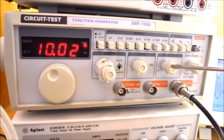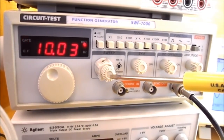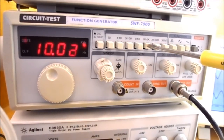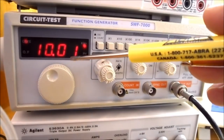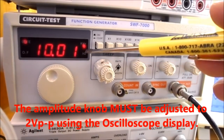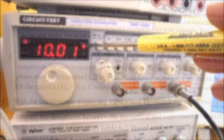All the knobs should be pressed in. This one should be fully counterclockwise till it goes click. You want the power button on. You want to select sine wave. You want the range to be times 10K. You want the OSC button in the out position. So we're going to rotate the big knob until we get as close as possible to 10.00. And we want the little indicator light to be on where it says kilohertz.